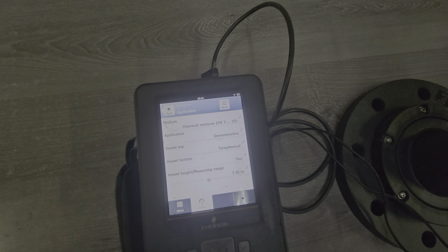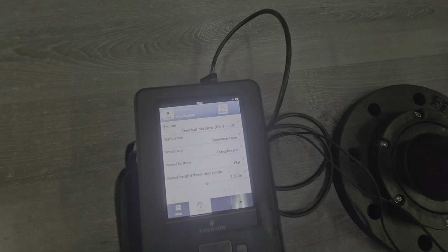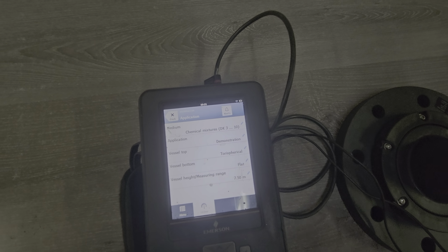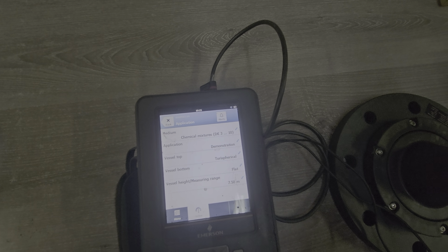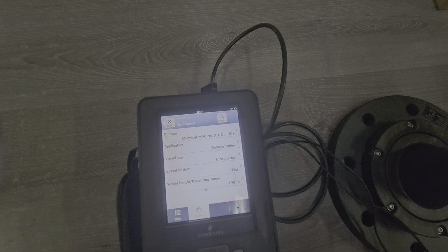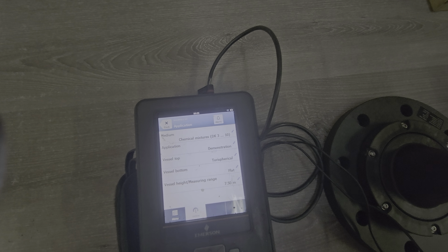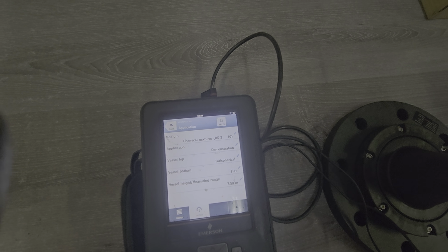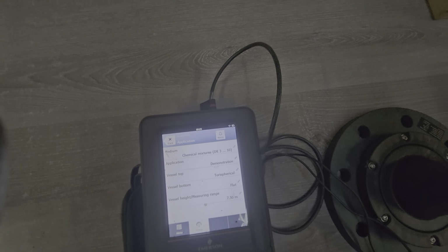That's where you define how long your tank is, so that the instrument can know the distance from the top side of the tank to the bottom side. That's basically your zero and your span. But you can always adjust those values. It does not have to match exactly the length or the height of your vessel, because maybe you want to set your 100% of the vessel to be not at the brim where the vessel is overflowing, but a little bit below. That's what you can do.